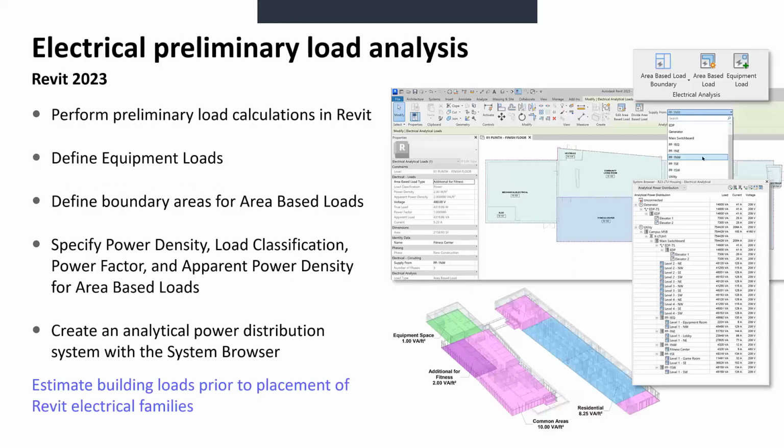Something that Mike is going to talk about later in the presentation, so I won't get too much into it, is electrical preliminary load analysis, right? So you can perform electrical loads right in Revit just by defining some areas, giving it some information, and have it do that work for you before you even place any of your families. So Mike's going to get into that in more detail at the end of our last presenter today.